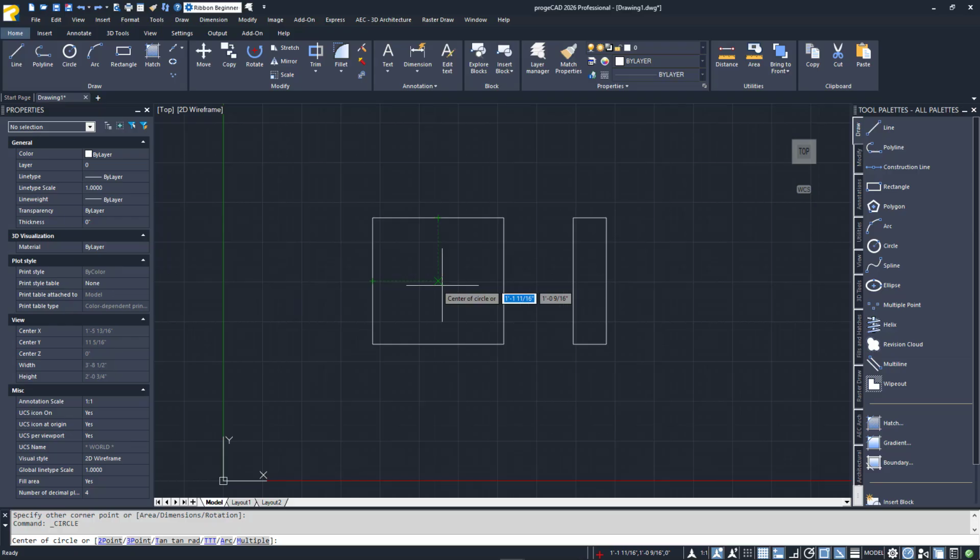Move your mouse into the center of the rectangle, and when both dotted reference lines are visible, you're in the center. Click to select the center of the circle and pull away to select a radius point. Again, it's a fast, accurate, and easy method to acquire reference points.